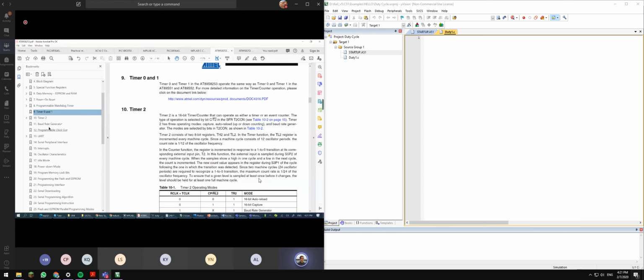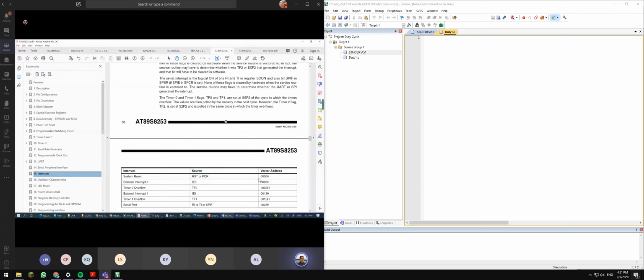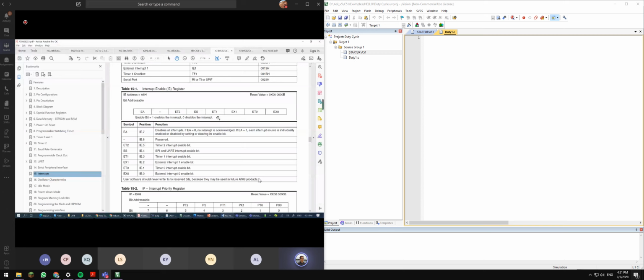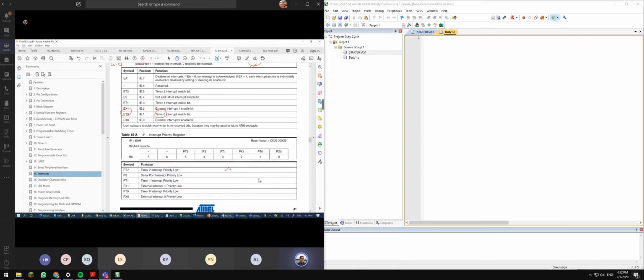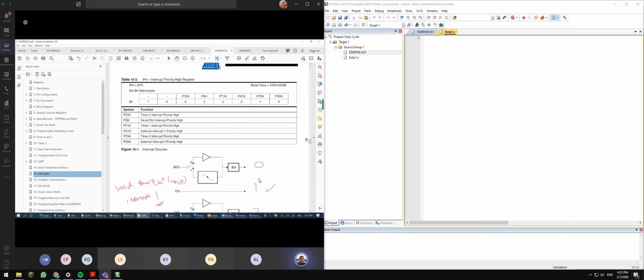We're back to the interrupt. As I told you this morning, interrupt is even more straightforward for this particular microcontroller. To enable the interrupt, you just enable the master interrupt, EA equal to 1. This is quite similar to GIE in PIC 18. And we need to enable the timer 0 interrupt, ET0. Basically, we just enable this bit and this bit for initialization purposes. This is for interrupt priority; for the moment we don't care about who comes first. I think basically that's all.